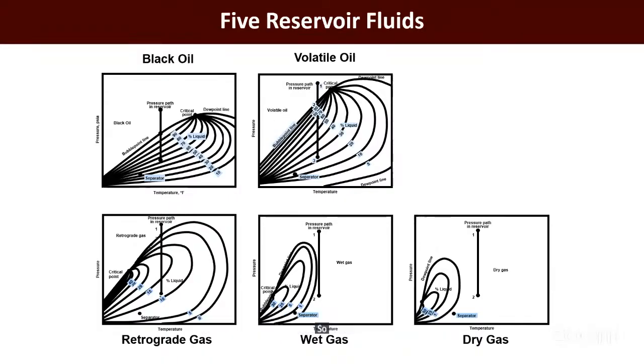So most of the books classify them starting from the dead oil. The dead oil, which is away from these five reservoir fluids, is an oil with very low gas dissolved. Any oil or any hydrocarbon has some gas dissolved in it. And if we reach a certain pressure and a certain temperature, we will see the gas get out free from this oil composition. And it's called bubble point pressure. And we are going to talk about this issue in detail.